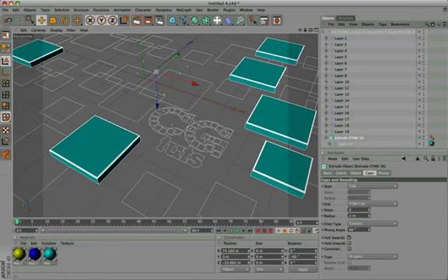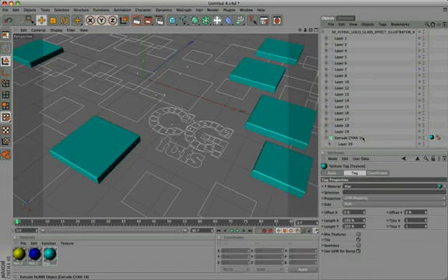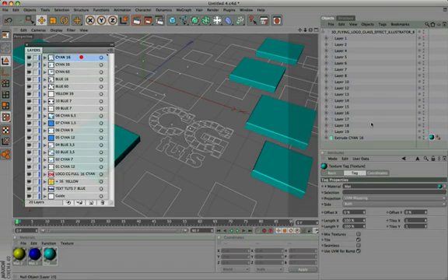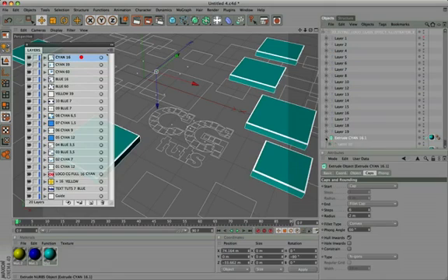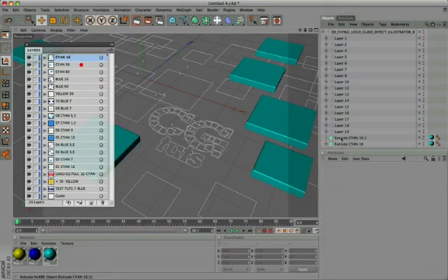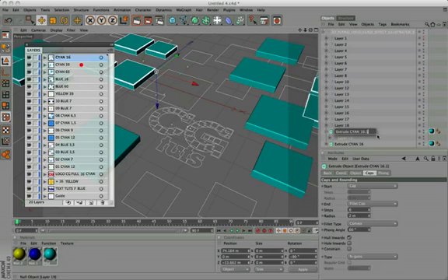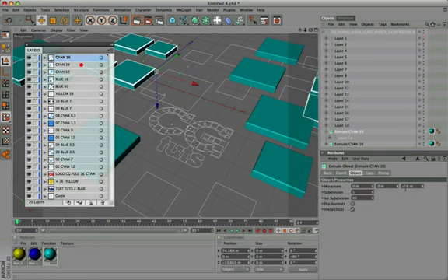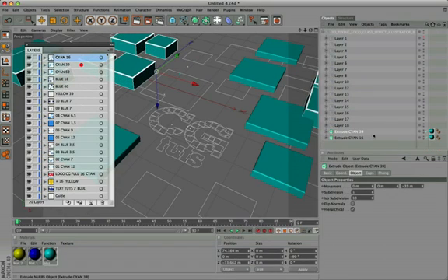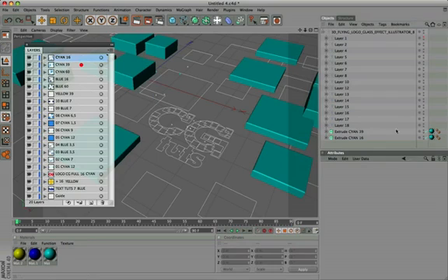Repeat the last step on all layers, following the scheme image, and enter the color and the extrusion value. Let's create the layer Extrude Cyan 39. Duplicate the layer Extrude Cyan 16, delete the layer inside it and drag in layer 19. Rename it Extrude Cyan 39. Change the extrude value from 16 to 39. Repeat this step for the layer Cyan 60.